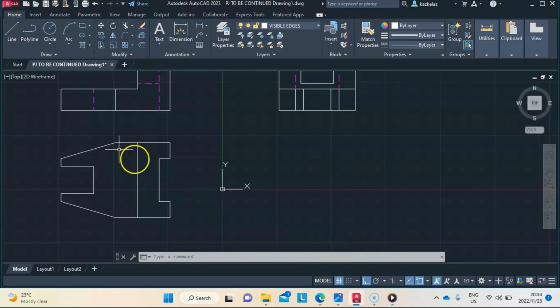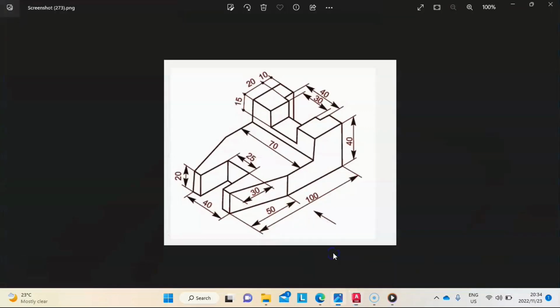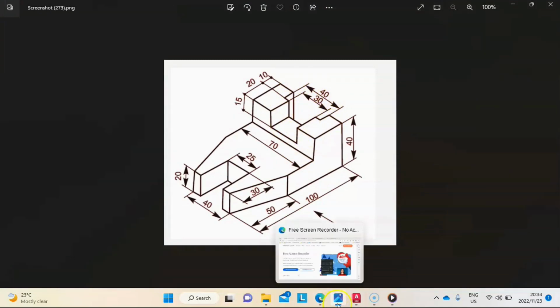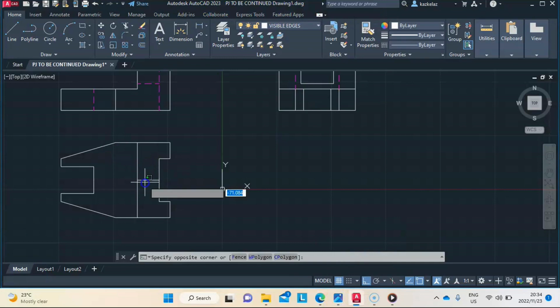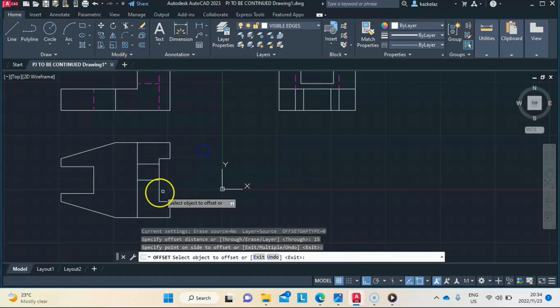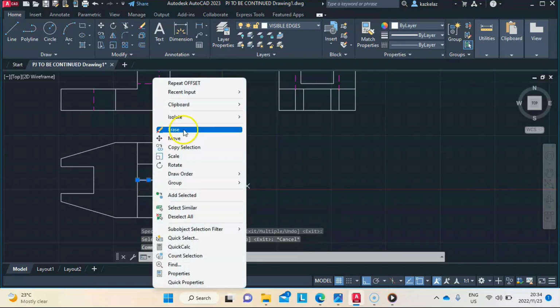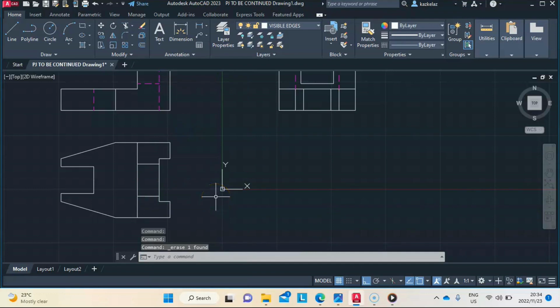That groove is straight. It's actually like this. So let me put a line there, right? I'll offset this line on either side. Let's check. It's 30, right? That groove is 30, right? So what we need to do is offset this line by 15 on either side of the midpoint, by 15 to that side, by 15 to that side, and then we're going to have something like this here, right? So that's basically what we're going to have.